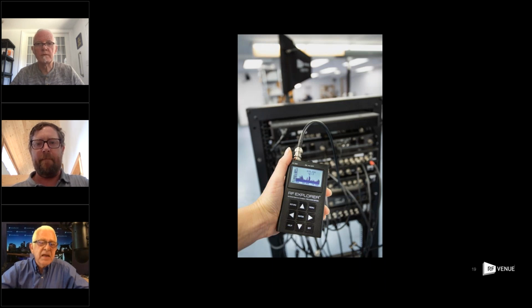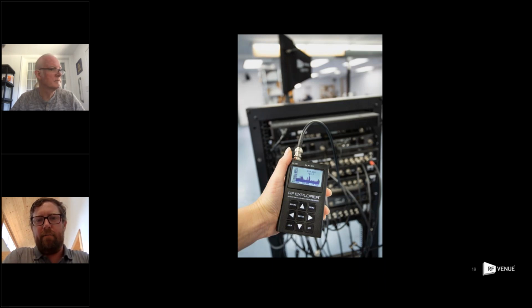Yeah. And at that level, you may look at one particular frequency and it doesn't look very hot, but if you've got 8 carriers in that same unit, plugging that into your spectrum analyzer, even though it doesn't look very high, is quite powerful. Right. And that's really the delineation between the receive and transmit sides, where the transmit side is a lot hairier than the receive side.